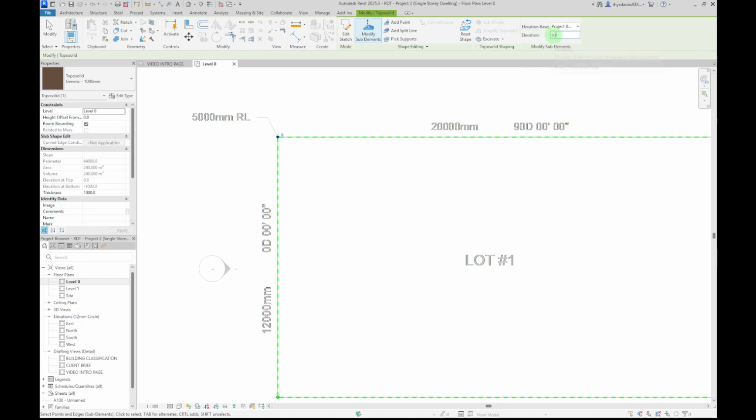You'll see here the elevation is 0.0. So you can assume maybe a height datum back to sea level. 0 would be the average of sea level, and in Australia we would call that the Australian height datum. But this RL here, reduced level, is saying 5,000 millimeters. So that's 5,000 millimeters above the height datum.